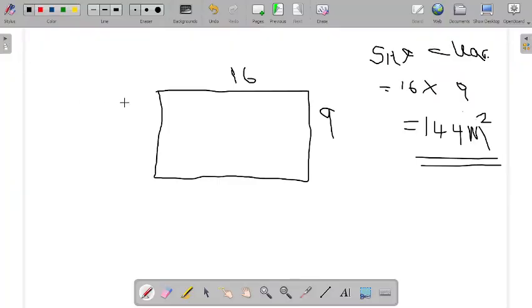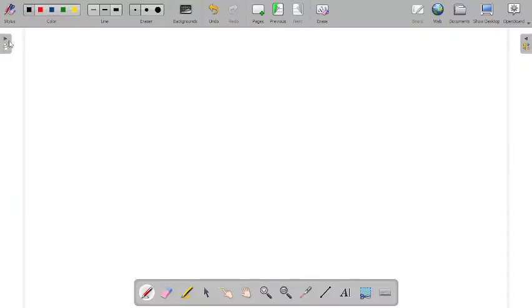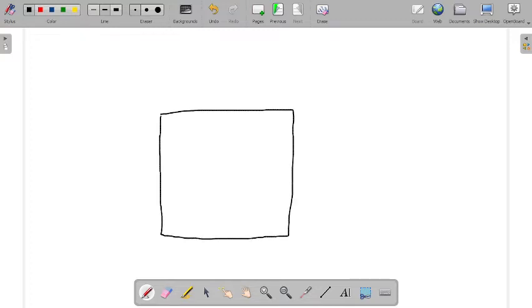So now what that implies is that the size of our building is here we have 11 meters, and here we have 10.7. That is the size of our building. Now, what I was explaining earlier, this is the size of the building. If you choose to clear only this portion alone, there will be no working clearance for you around that building. So you need to add the working clearance to it.